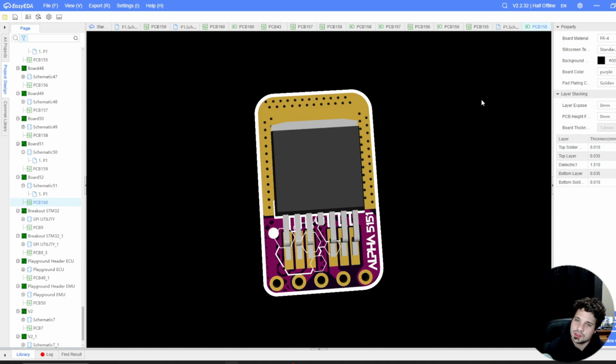So when the ECU is going to say that VTEC turns on, it sends out a logic level. In some cases, we borrow an external output, maybe like a power steering sensor, and that sensor has a high enough logic level that it can turn a relay on. So the ECU sends out this small logic level signal that is either on or off. Let's think about a 1 or a 0 because that's how logic signals work. When it's a 0, it means off or ground. When we have a 1, it means high or on, which is a positive signal, usually set above a certain threshold.